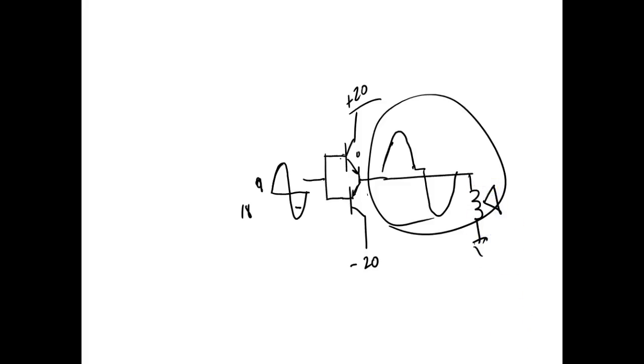And these are the guys right here. This is what your stereo has in it. This is what your audio amplifiers have in it. In your TV and all kinds of stuff they use. But this is a Class B, and this is a Class B, but it gives us an output that appears to be a Class A, right? You understand? So we call this guy what? This guy is called an AB. So just about all your outputs on your stereos and stuff like that are AB amplifiers.